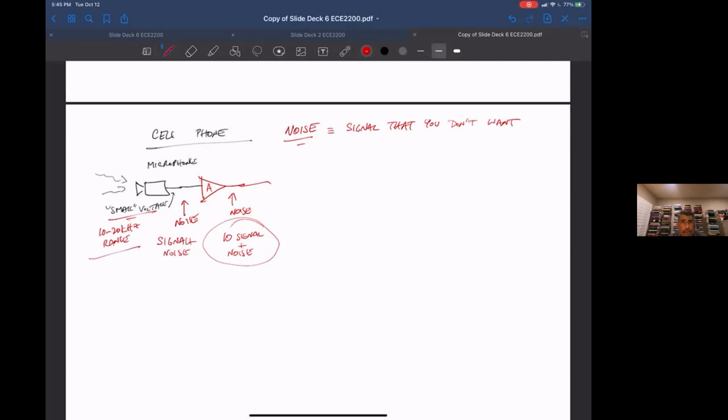And a typical size for antennas is about 1/4 the wavelength of the signal you're transmitting. The upshot is that if you try to transmit your 10 to 20 kilohertz audio signal directly, you need an antenna the size of a football field or something, a very big antenna, because the antenna size is proportional to the wavelength, and the wavelength is inversely proportional to your signal frequency.